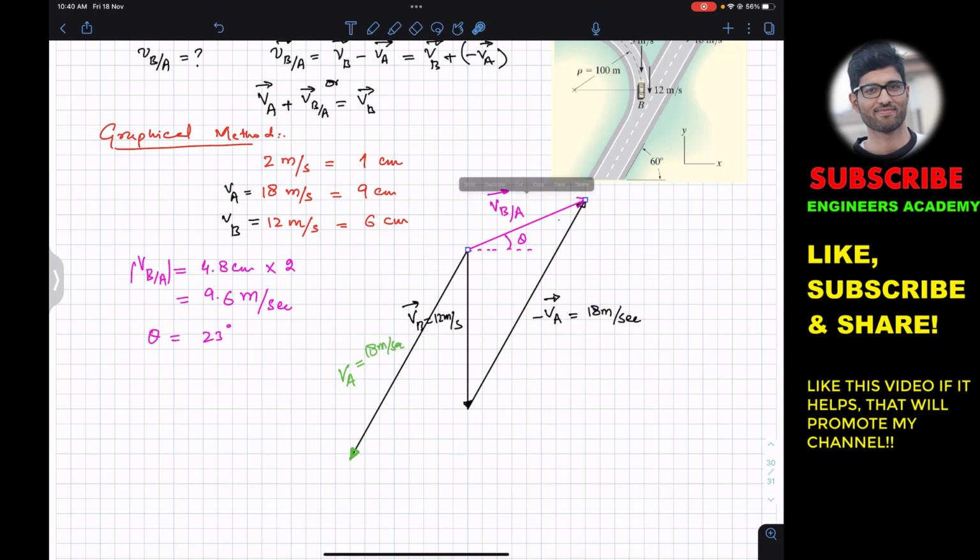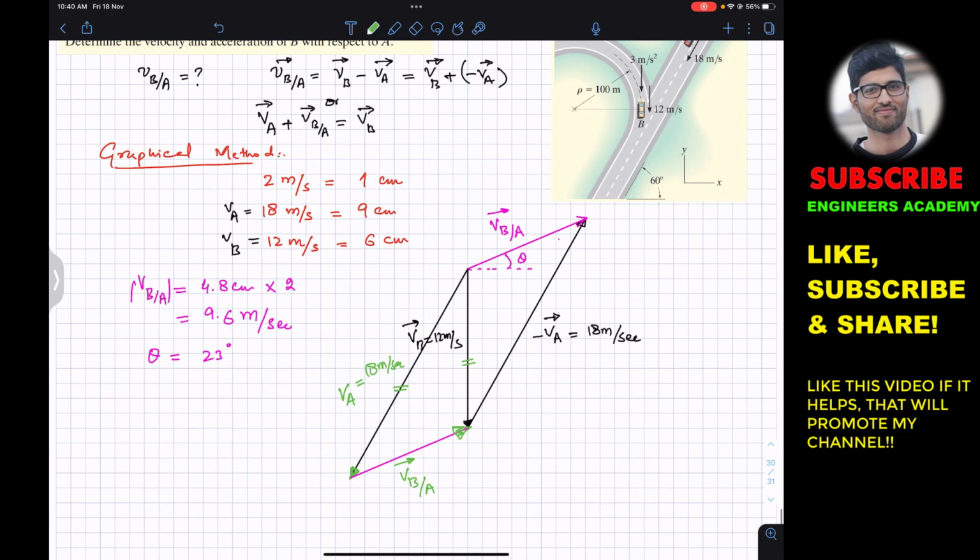So now if I copy this resultant, which is VBA, and place it here, we will get that same length. And this time, this will be in this direction, right? This is VB, this is VA, and this is VBA vector. Now it's up to you. Both will give us the same answer, since both of these equations are the same equation. So this is now VA plus VBA is equal to VB. And according to this equation, this is VB, this is minus VA.